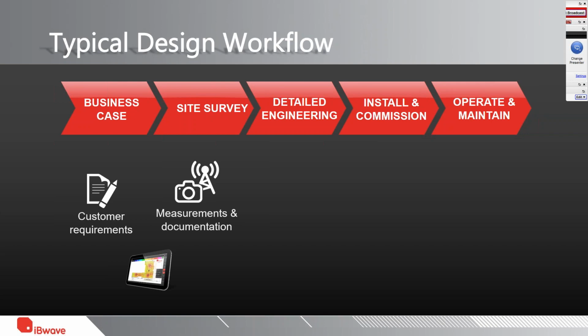This is where you can really leverage iBwave's mobile tool to bring in a floor plan, assign a scale, use the auto placement to achieve a certain criteria, which can give you an approximate number of access points that you need. Based on that, you can come up with an estimated cost and see, okay, does the business case pass or not? If so, and in many cases, of course, it does. If not, we can adjust the design to make it fit.